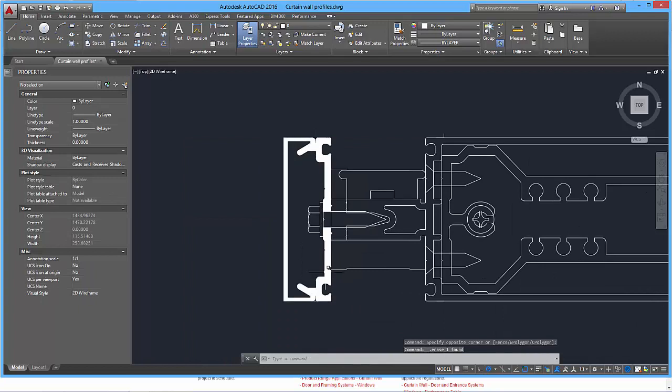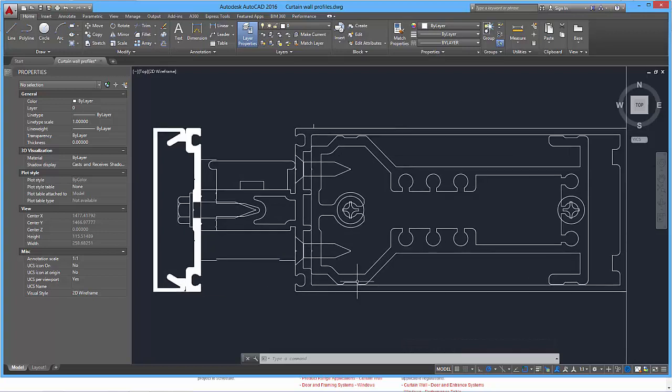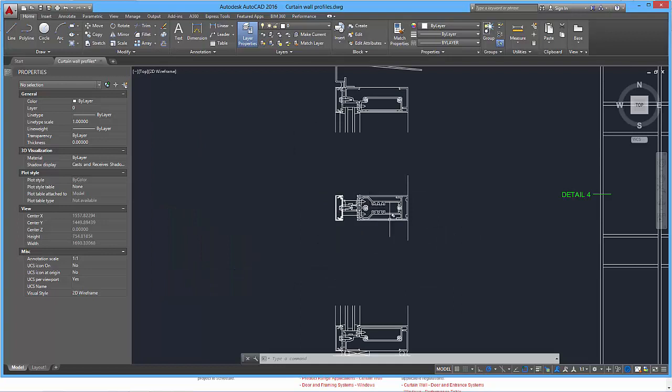Okay, so it's not necessarily that you have to do it the way I'm going to show you, but the reason I'm going to show you this technique is simply because you might want to use it for other things where we use pick lines and create a filled region of a complex shape. Okay, so we'll leave AutoCAD and go back into Revit, and then we'll look at the Revit detail family environment.